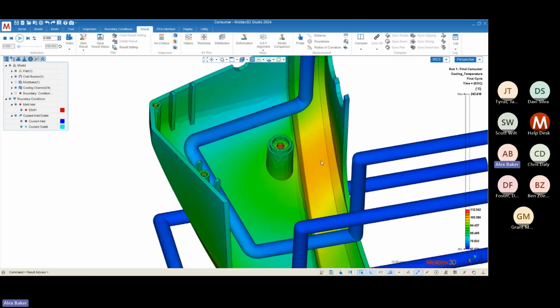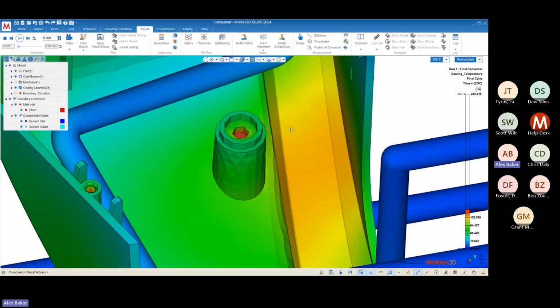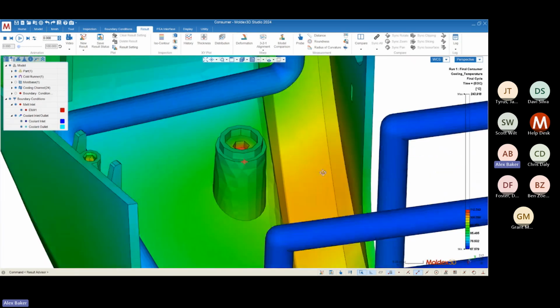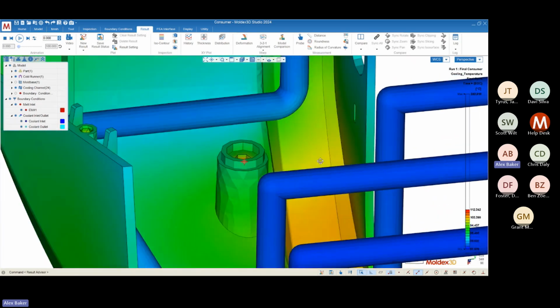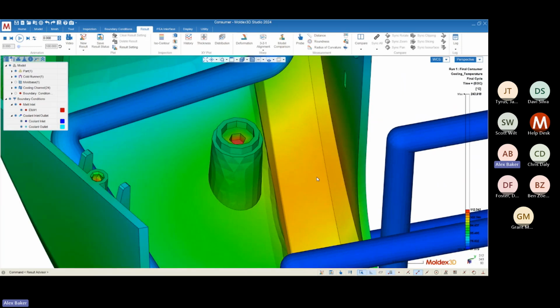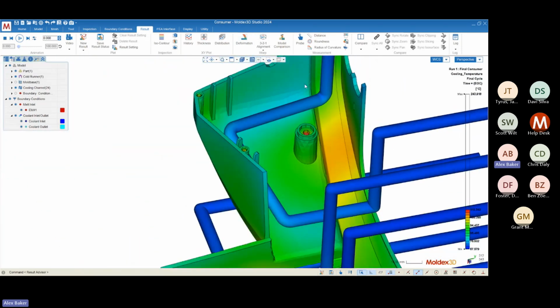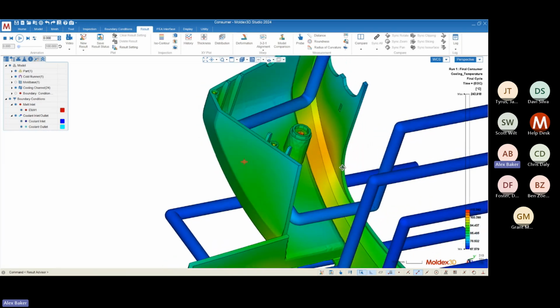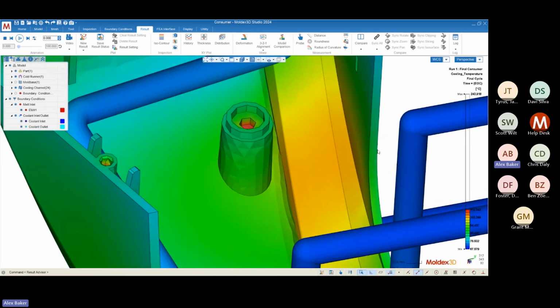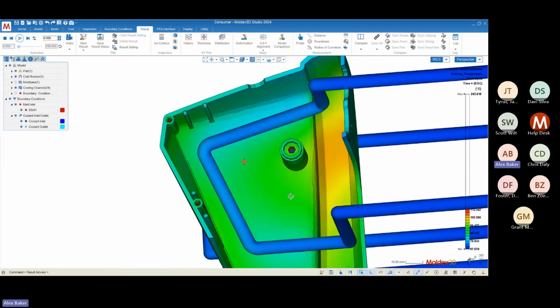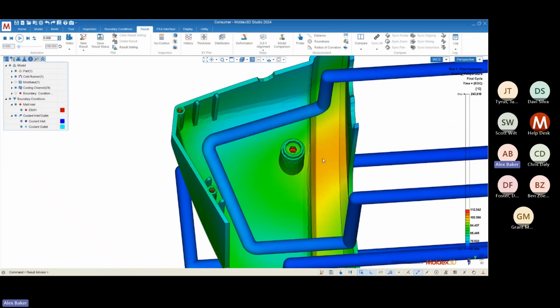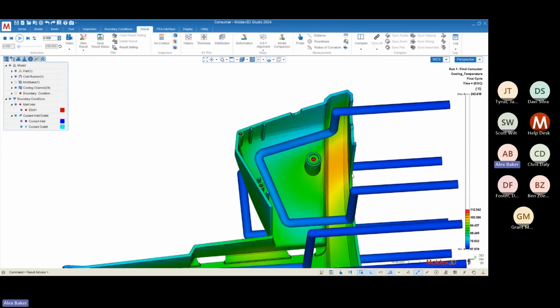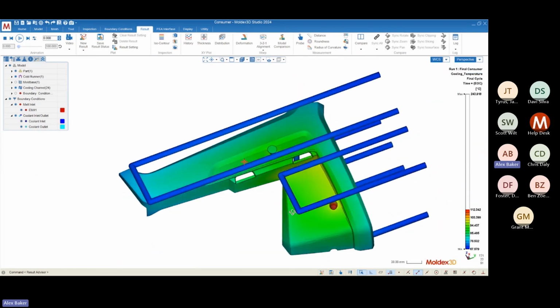The heat actually is going to accumulate in locations on the part where there's not a cooling channel, and eventually that heat might be pushed out to the cooling channel, but it's going to accumulate faster than it pushes. So it's very common for even a conformal system like this to have a hotspot, just because there's some feature on the geometry that is not being adequately addressed.